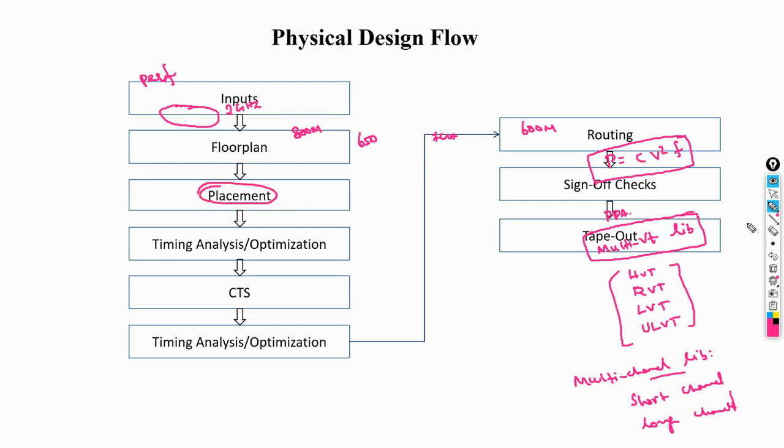For example, after placement there is something called area recovery that you can do. That helps with timing non-critical paths, reducing the cell areas, and eventually leads to less area and less power. Again in CTS, you might be interested in choosing the right cell, the right transition and the right skew, which eventually bring down your clock tree power.